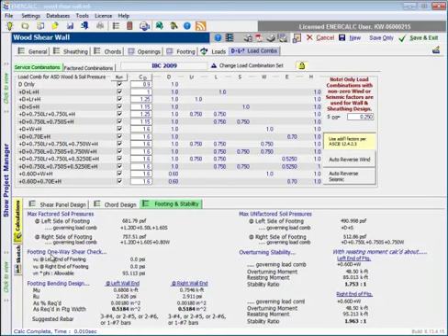Next we have footing one-way shear check, where we report the shear stress at the left end of the footing and at the right end of the footing. In this case, I believe that I've left my footing projections very short, and based on the projection length and the footing thickness, we're at that aspect ratio where there really is no shear stress. So that's why we're seeing 0 values here. But in longer projections of more substance, we would actually see shear stresses being reported, and then we see a phi-VN value that we can compare those to.